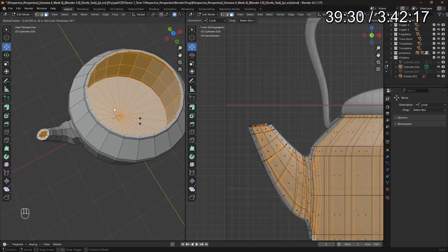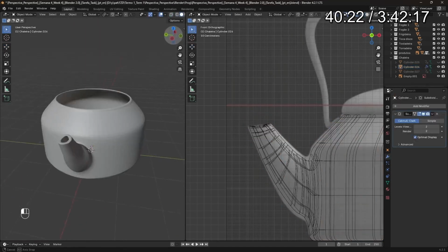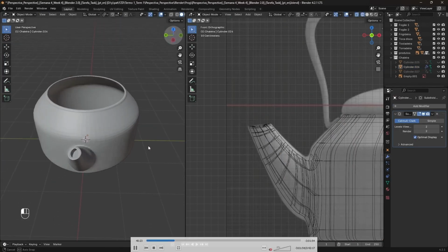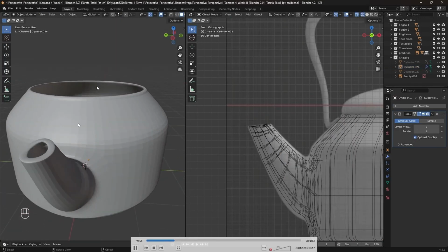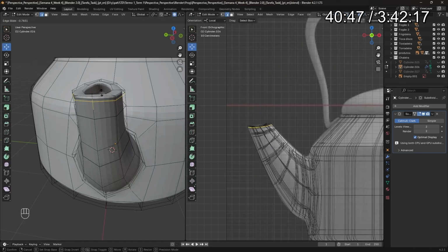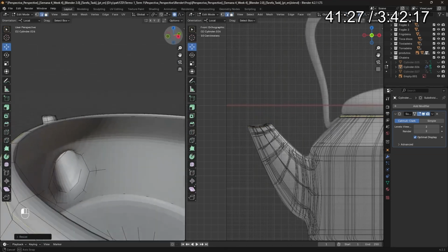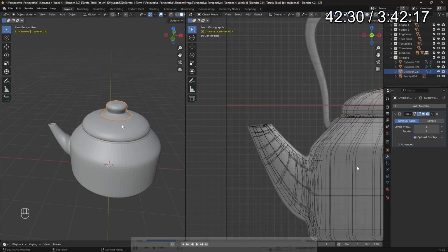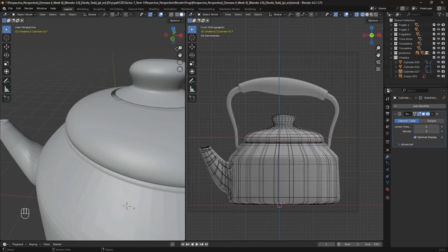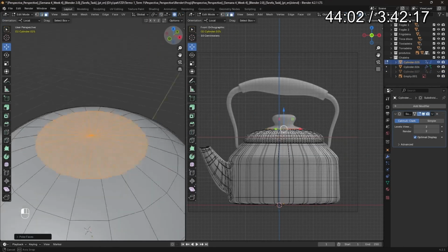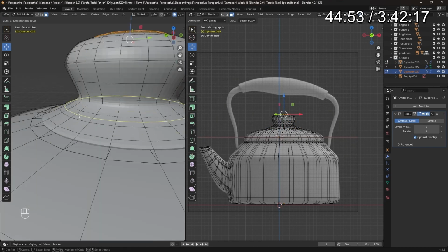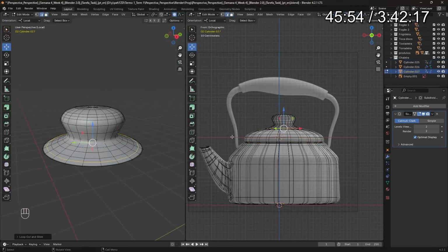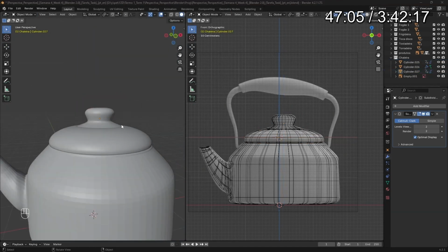And I created new cuts, and then I applied the subdivision surface modifier. So yeah, you can see that this is working well. After that, the idea was to add new cuts and also work on the remaining part. So I added the subdivision surface modifier to this part also, and I just created new stuff and new cuts to the mesh that I wanted.